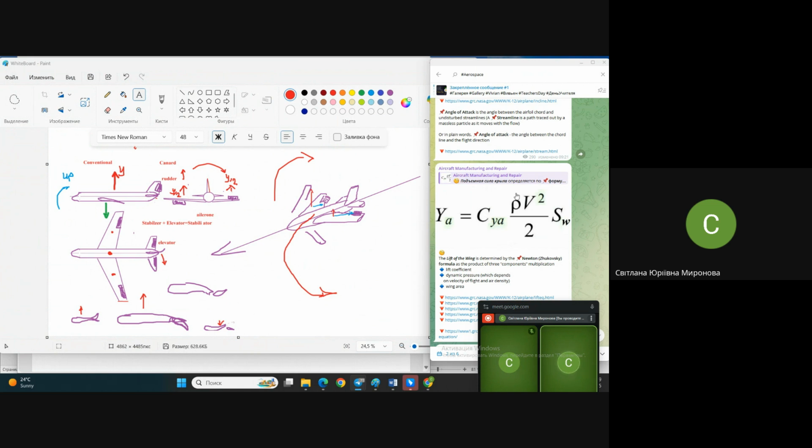Let's talk about takeoff first. During takeoff, the speed can't be so high right now. We are still running on the runway and increasing the speed. But we remember that in order to take off from the airfield, we need lift sometimes much greater than the aircraft weight. It means that at this moment we really need huge speed, much more than the speed of horizontal cruise flight.